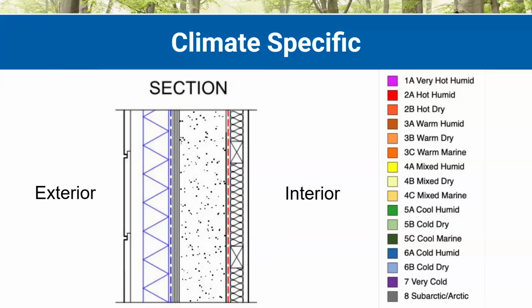So those projects that are really getting tunnel vision on the R value and that are spray foaming and/or running exterior rigid foam, they're having a really high R value, but they're losing the importance of that vapor control or that air sealing. And it could be trapping moisture. And even though it's a super insulated wall, that trapped moisture is really, really dangerous. And even more so because it's super insulated. So that is increasing the risk by super insulating. We need to really care about how it's drying through diffusion. And in these more northern climates, we really don't want to have exterior vapor retarders. We're really mainly drying outwards most of the year.